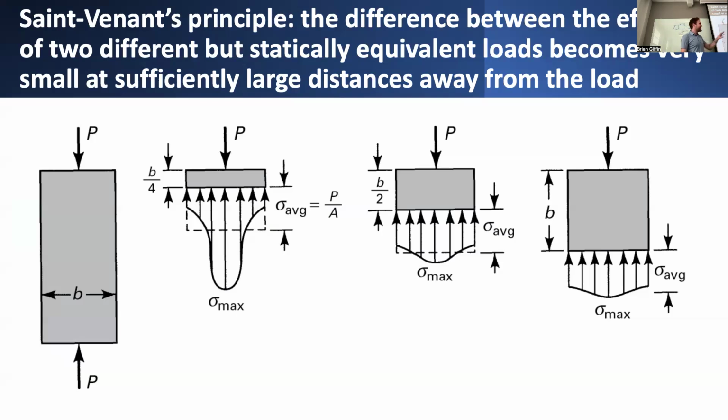And it makes it such that you can guarantee that as long as you're using a specified, standardized set of connections, the member is not going to fail at the connection location. If it is going to fail, it would have to fail somewhere along the length. If you're designing the connection, you've got to do the work yourself, though. So it depends on what you want to do and what you're asked to do. But yeah. All right. So yeah, go ahead.